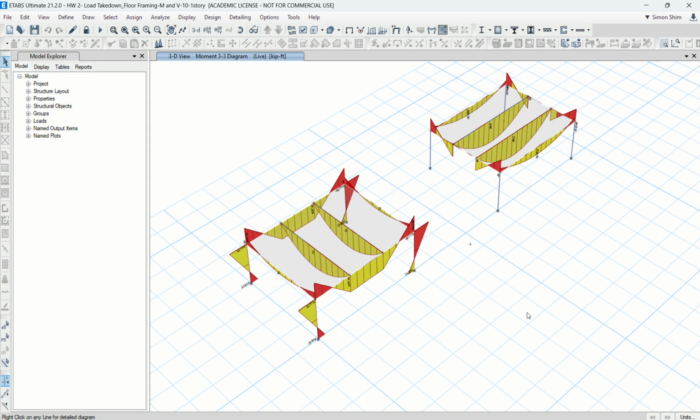So in our case, the pillar-beam is a pin-pin connection, right? You studied this, you know what a simple pin-pin connection is. No moment resistance. That's why zero moment, zero moment. You have a maximum moment here, right? What do you mean by negative color? Then the negative moment. So, eventually. Failure?